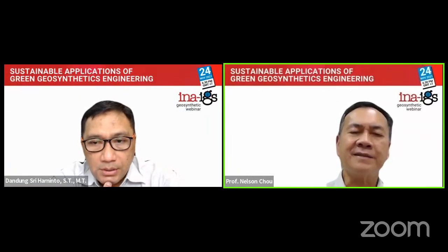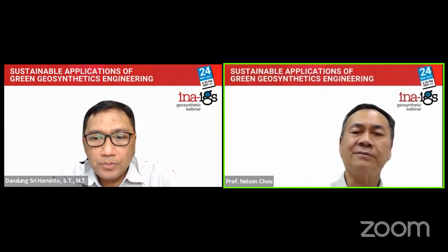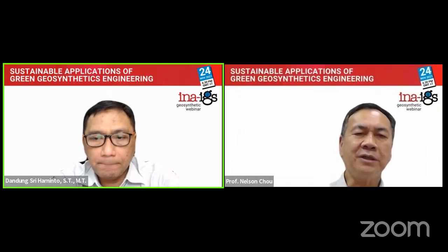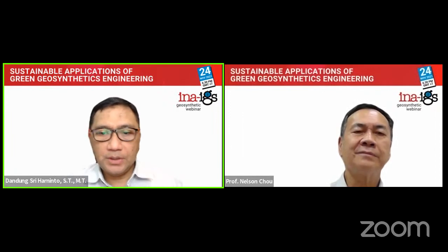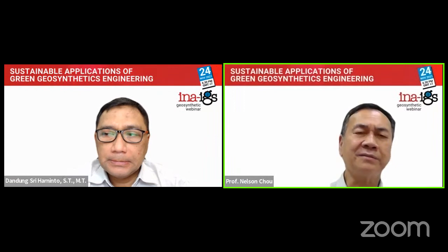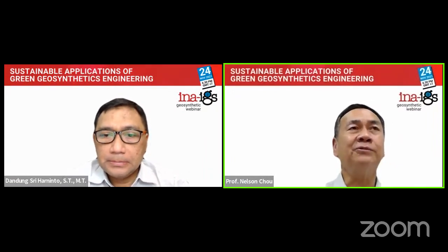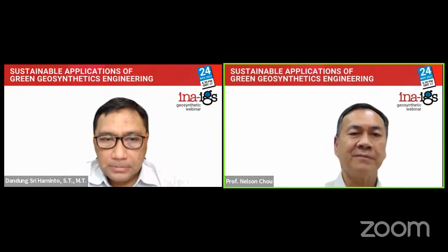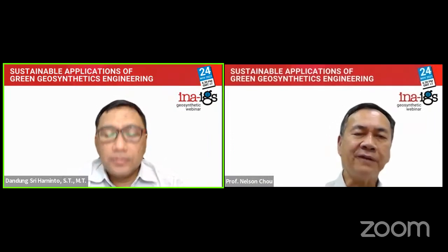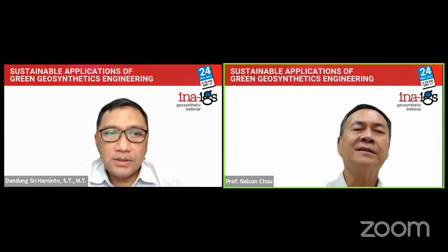But in case the foundation soil is very, very soft, then you need some treatment, especially for the whole area, if the settlement just cannot be avoided. Geosynthetic cannot avoid settlement, but can reduce differential settlement. Okay. This is the key answer.